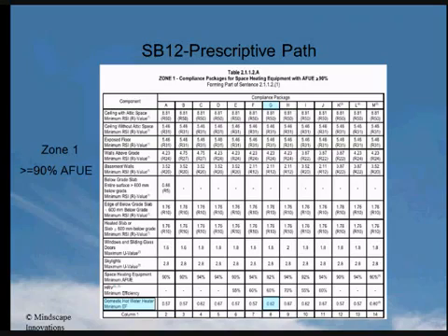I would now like to talk about several special cases, packages K, L, and M, which are cases for homes using insulated concrete forms for walls, or using a combined space and water heating system. Package K is for a house whose basement and above grade walls are made of insulated concrete forms, or ICFs. That house may also choose to comply with any other package and is not limited to only package K. Package L is for a home that has a basement built with insulated concrete forms and may choose to pick any other package except for package K.